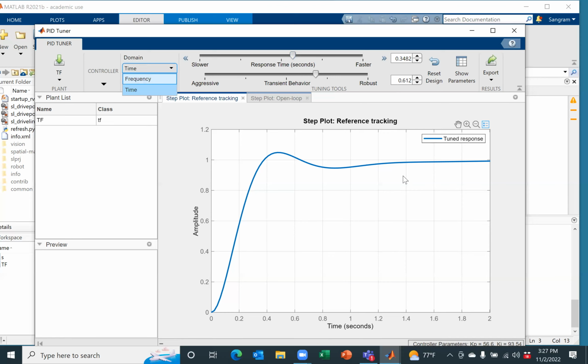Any questions here? For linearization, do we use something like a Fourier transform? You can do linearization in a lot of ways. Linearization is just finding a linear model of a nonlinear system. So you can use a numerical linearization, or an analytical linearization. You can also use some type of Padé approximants, and then you can find the linearization.